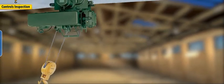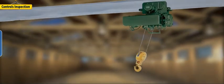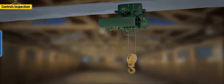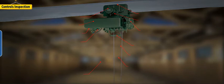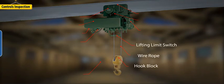After visually checking the crane, operators should test the crane's controls and limit switches. Limit switches are safety devices that prevent the crane trolley from moving too far in one direction and the hoist from moving too high. Test these by moving the crane in all directions and raising the hoist until the limit switches trip. Also test the hoist brake and the trolley movement.